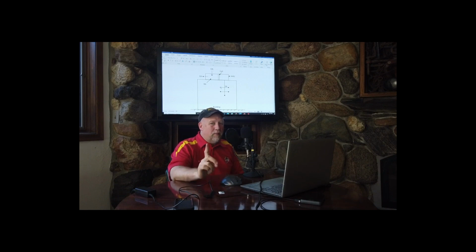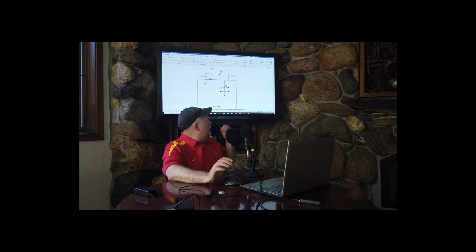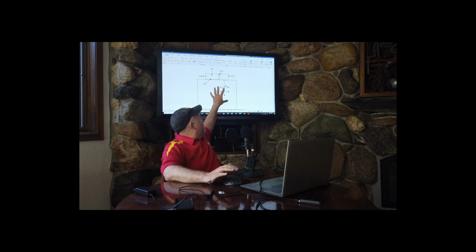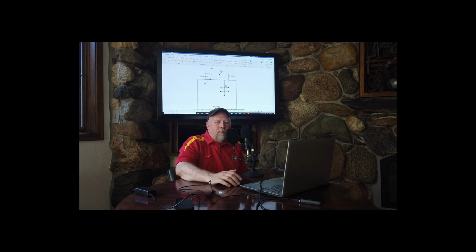Latent energy produced by people, and then latent energy that's coming in through infiltration. Compared to the rest of the loads, lights, conduction, solar, radiation from people, and lights and infiltration, compared to the sensible heat gain, the latent is fairly small. Changes a little bit when we bring in some outside air from the outside in summer, but for the room, for the space level, the loads are mostly sensible.